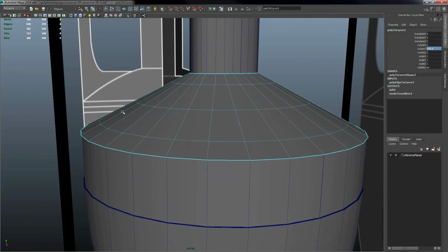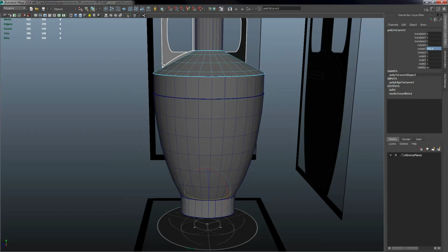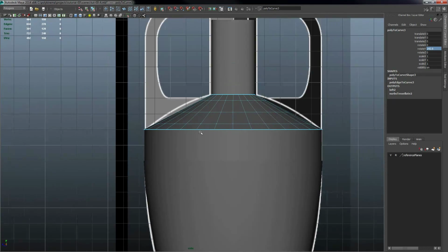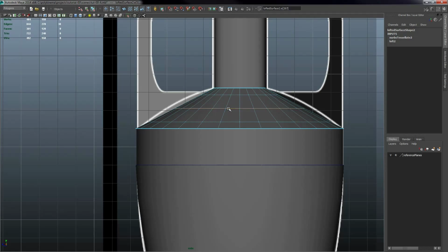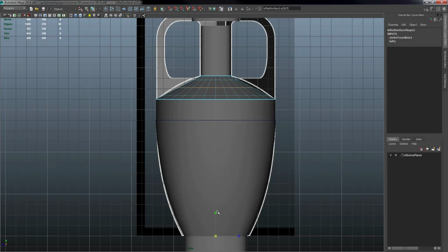And I'm going to do the same shape alterations to match that rounded shape of the top of the vessel there. And I'll do it in the side view again. Now, the scale tool is still down here at the scene origin, and holding down Control I can scale those edge loops to match the more curved shape of the lid of that vessel.